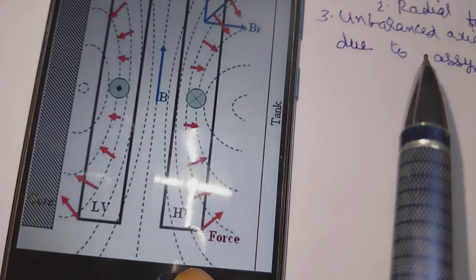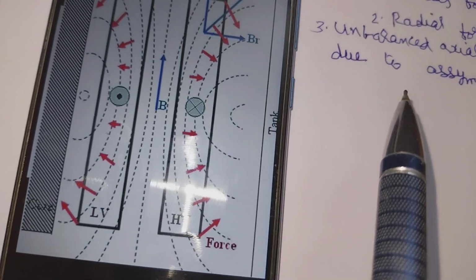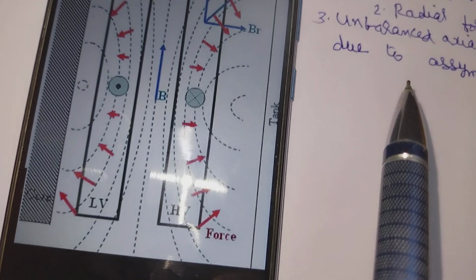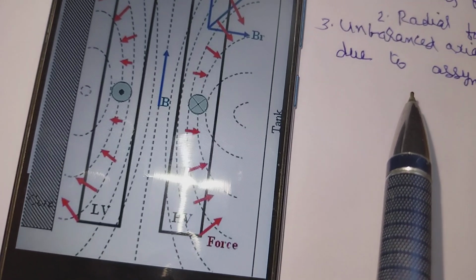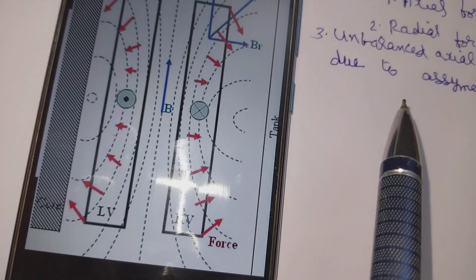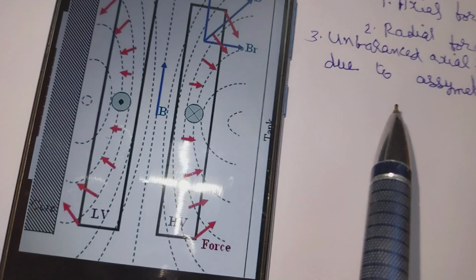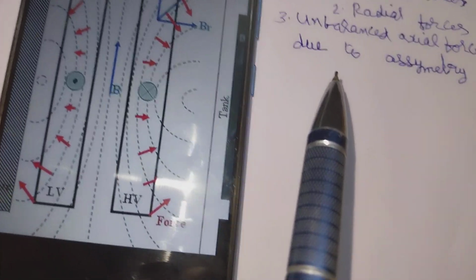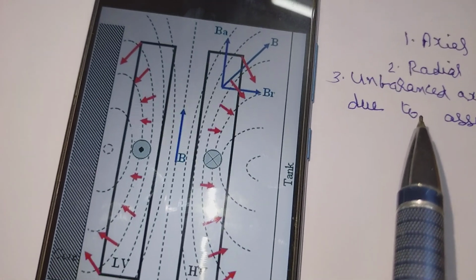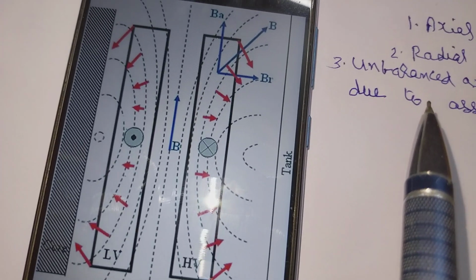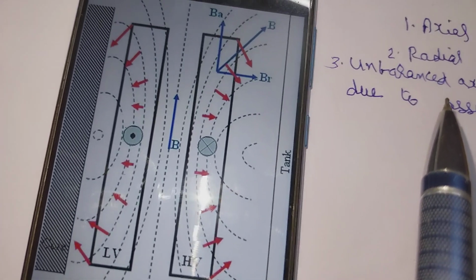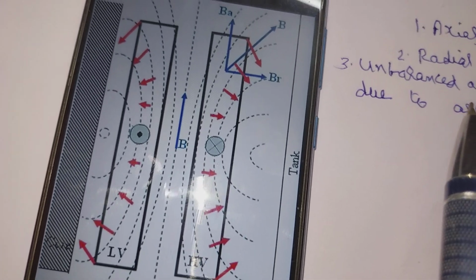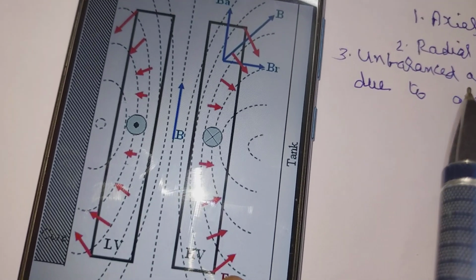But when large transformers are subjected to short circuit conditions at full voltage, the short circuit currents may reach 10 to 25 times the full load value, with forces 100 to 625 times the normal value. Under such conditions, the mechanical forces become so great that it is possible to wreck the transformer, and unless the coils are solidly pressed, they are bound to fail.